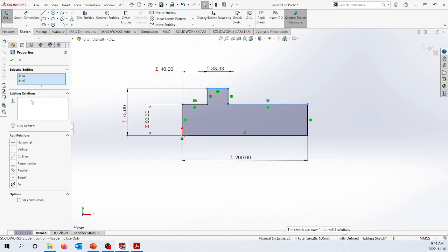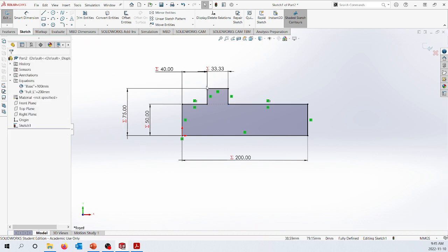So if I delete that collinear, it goes back to being happy. So if you ever see red or yellow showing up in your diagram, it means you're over-constrained or you're attempting to make impossible geometry, that it can't mathematically do both, like you're saying, I would like you to be vertical and horizontal. It's like, I can't be both of those things. Please stop. Please remove one of these. I'm getting stressed. Okay. Bit of a tangent.